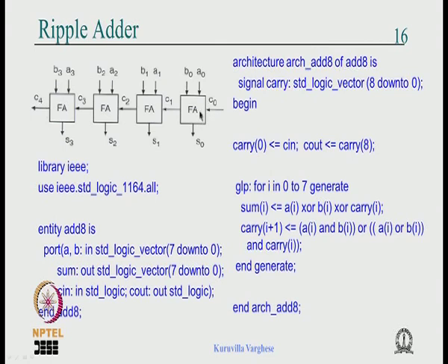So if you assume 2 levels of circuit in each of AND and OR, then you have 8 gate delays by the time you come here, and you can imagine if you go to S7 you will have 16 gate delays, and that adds a lot of delay. Okay, so there are adders which give less delay, and so this is simple.